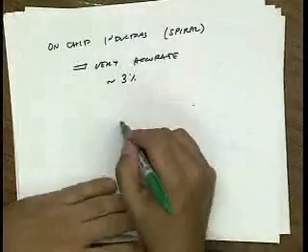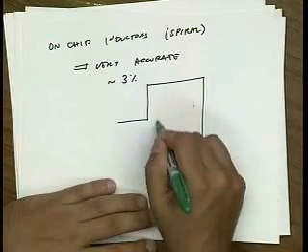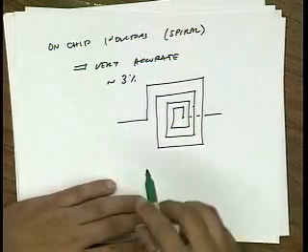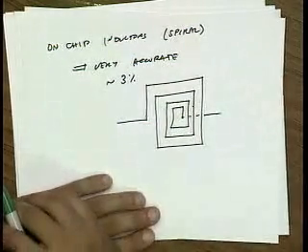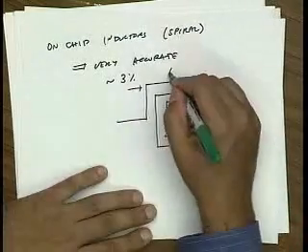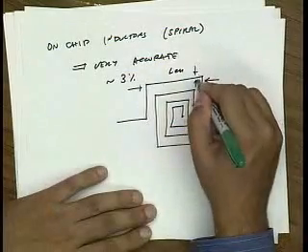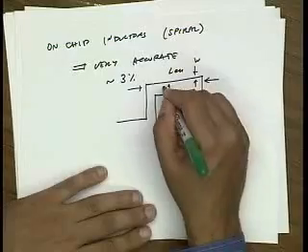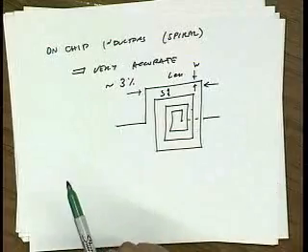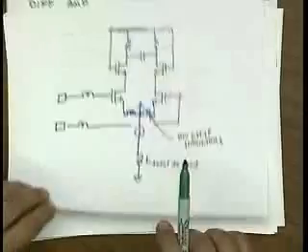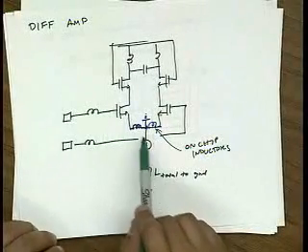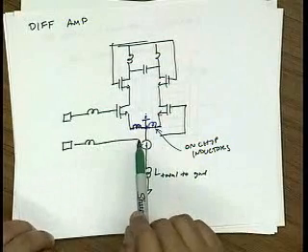And that's because the way we build these inductors is we build either square spirals or polygon spirals. It has to be a planar structure, so we have to make it in a plane. But the inductance is more or less a function of these dimensions, right? Let's say the length, the width of the conductors, the spacing of the conductors. And these are very well controlled in an integrated circuit process. And that's why the inductance value is so accurate. So I can synthesize a very accurate degeneration inductance here and synthesize a very accurate real component of the input impedance with a differential topology.